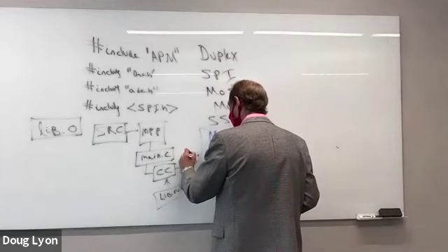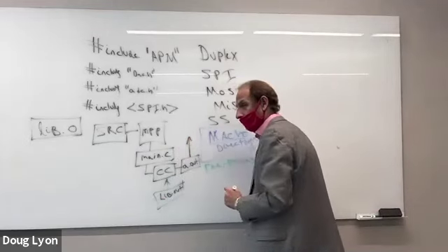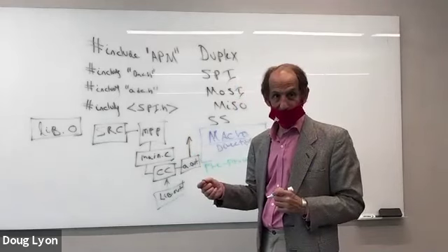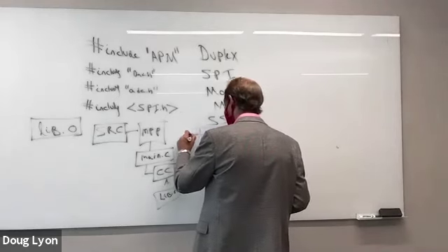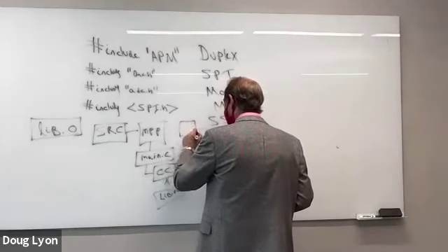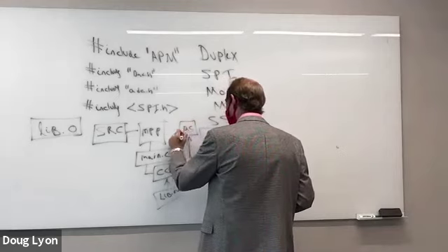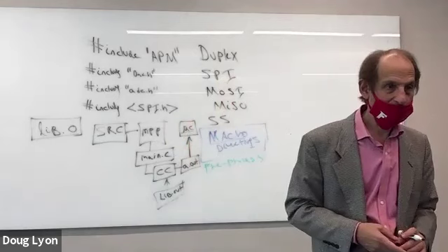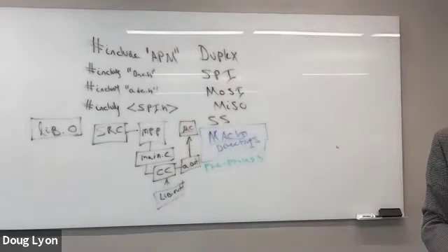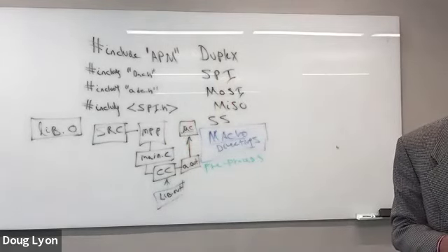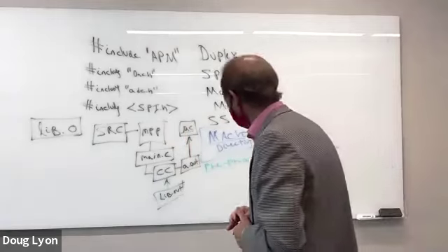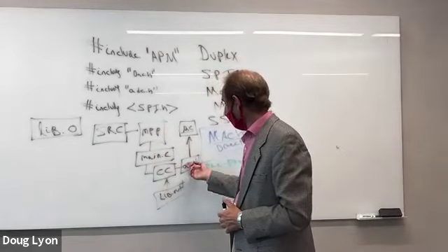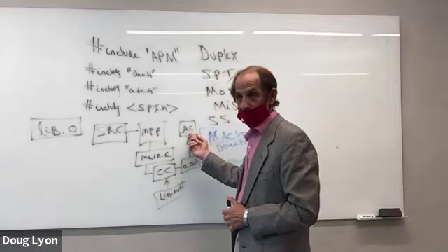introduces a linker. Then you have a communication path which goes to the Arduino, and you can change what that is, but somehow the a.out gets downloaded into the microcontroller. And then the microcontroller starts to execute the a.out. That's the basic flow. Compile, link, and load. So here's the sort of compile stage with the linking built in and then loading into the microcontroller.